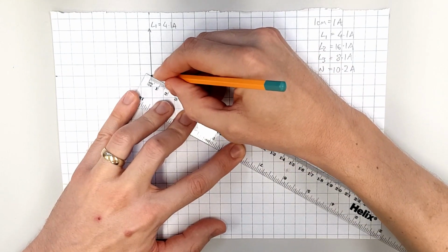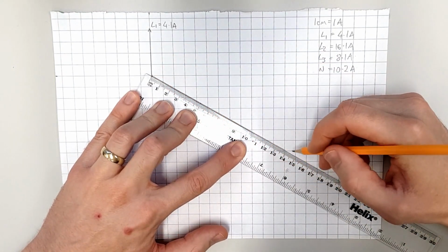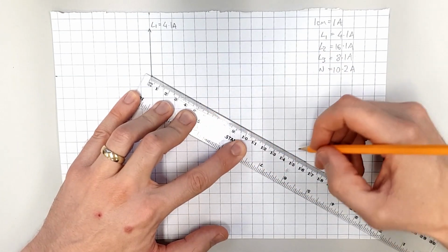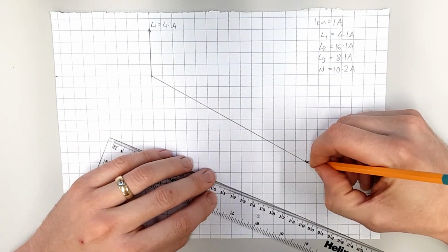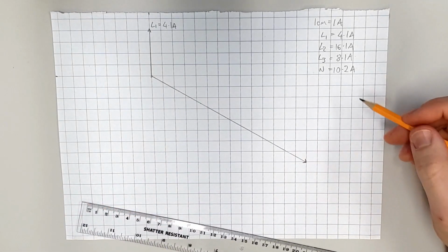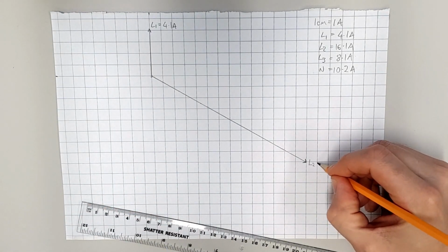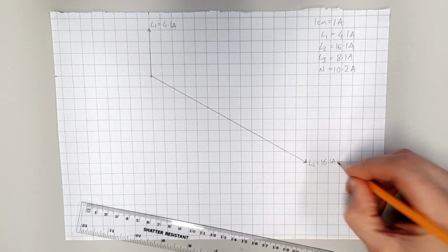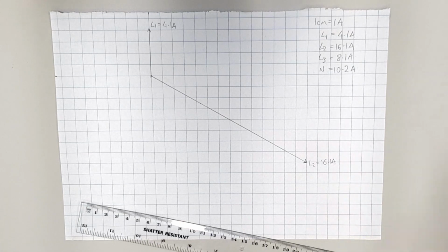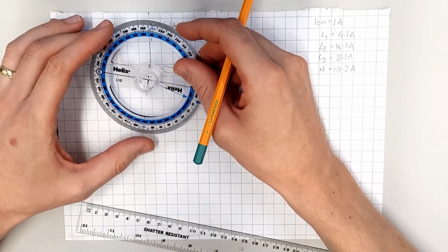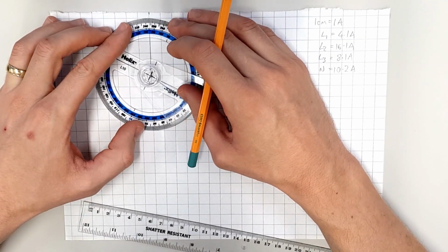As I say, it's not strictly speaking necessary to draw this method to scale, but I'm just doing it A, because I quite enjoy doing it, and B, because it helps us to visualise exactly what's happening with this circuit. So that's our L2 value, and that line is 16.1 centimetres long, which represents 16.1 amperes. And then finally, I'm going to draw at an angle of another 120 degrees from my second line here.